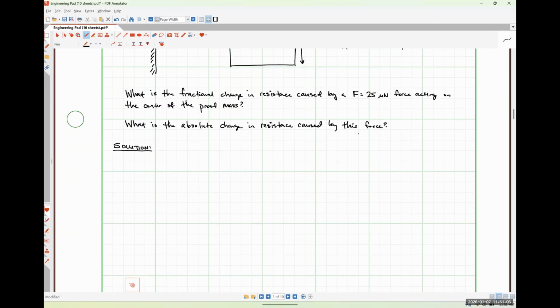So going back to our notes from looking at cantilever beam deflection, we should be able to see that our maximum stress, σmax, is given by the expression F times L times t over 2I, where, just to be clear, L is the distance from the anchor point to where force is applied.